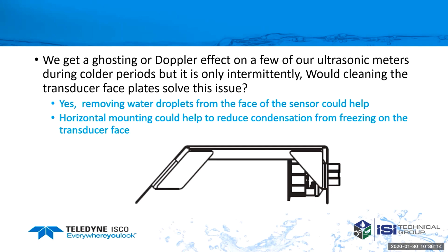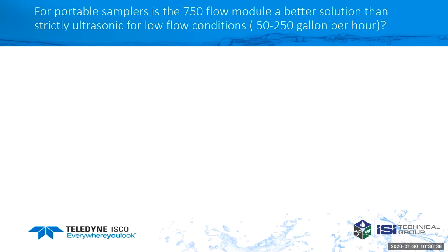You get water droplets developing on the face of the ultrasonic transducer. The water droplets can freeze, and then that could cause some problems. So one thing you can do is we sell a horizontal mounting bracket. And so if you mount it horizontal, now those water droplets should go to the bottom of it and stay away from the face of the transducer. So that could help minimize that problem.